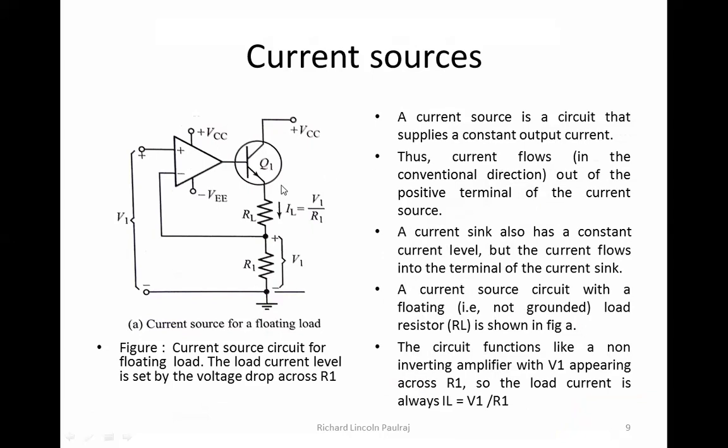Fine. So now let's look at the circuit here. It's almost pretty much the same. We have an op-amp and a BJT setup. Always keep in mind, whenever we are thinking of load, the capability of carrying a load, then I am looking at BJTs alone. There's nothing that matches BJT's performance with respect to load carrying and current handling capabilities. So I make a combination here along with my op-amp and BJT. I power up the BJT, I give plus VCC.